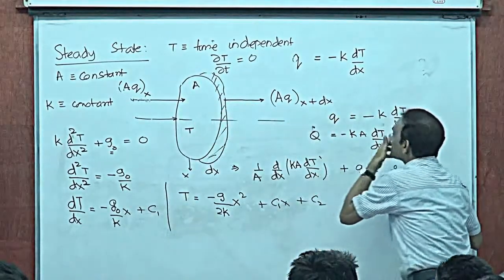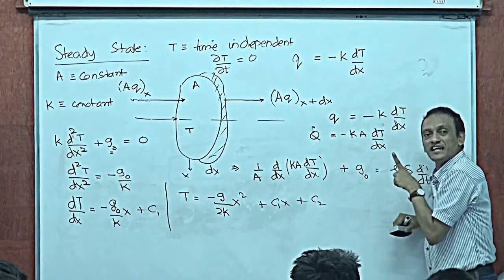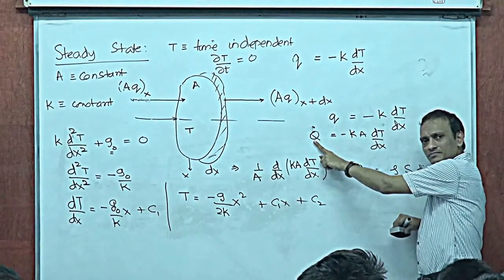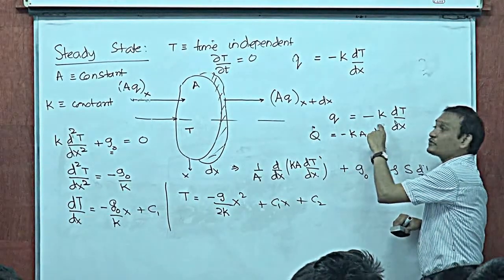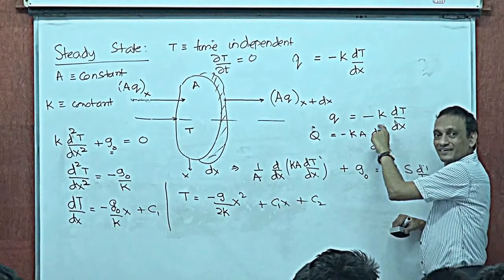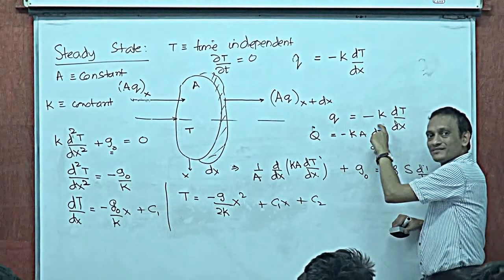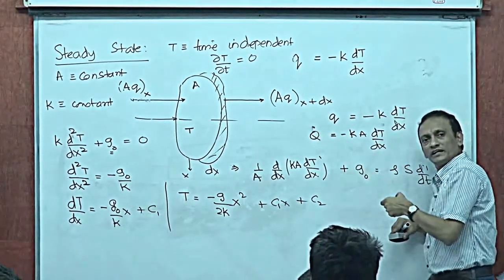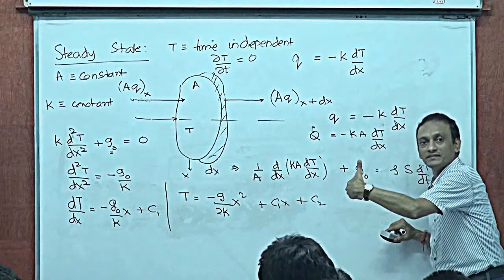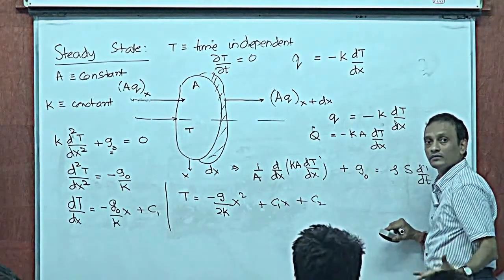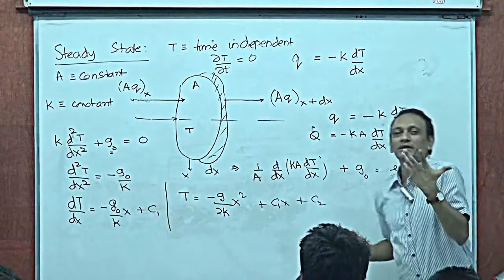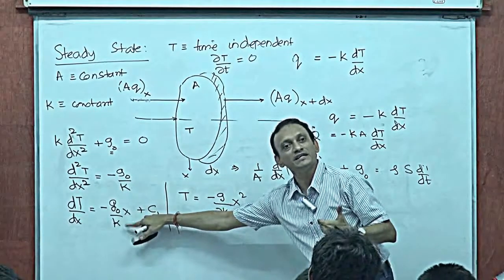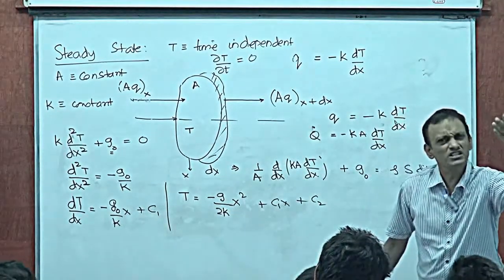Now realize that if conditions are steady state, then q dot at any x would be a constant. That means dT/dx would be a constant. So the temperature over a change of x, no matter where you take that change, the same change of temperature would take place, right? Essentially it's because of this factor that temperature is varying with x, but faster now. Do you realize that?